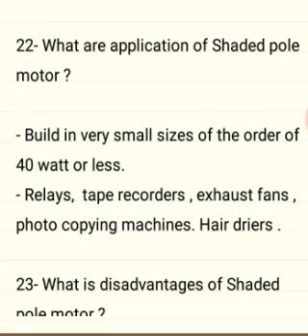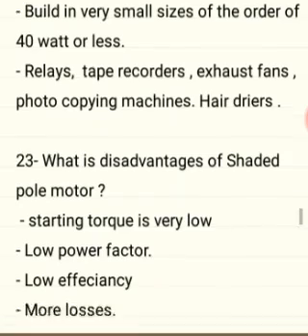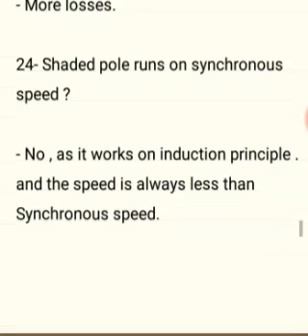Built in very small sizes of the order of 40 watts or less: relays, tape recorders, exhaust fans, photocopying machines, hair dryers, etc. What are the disadvantages of a shaded pole motor? Starting torque is very low, low power factor, low efficiency and more losses. Does a shaded pole motor run at synchronous speed? No, as it works on the induction principle and the speed is always less than synchronous speed.